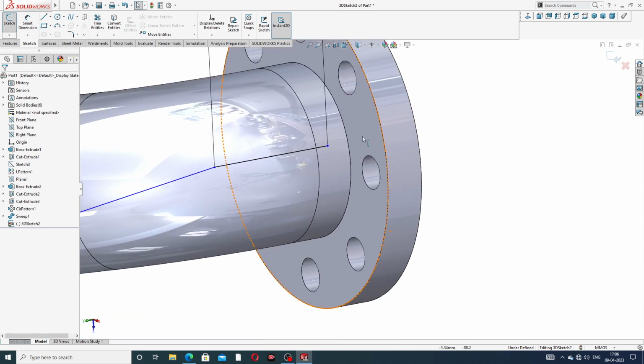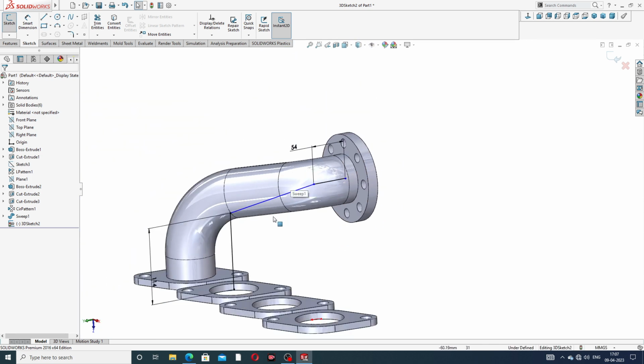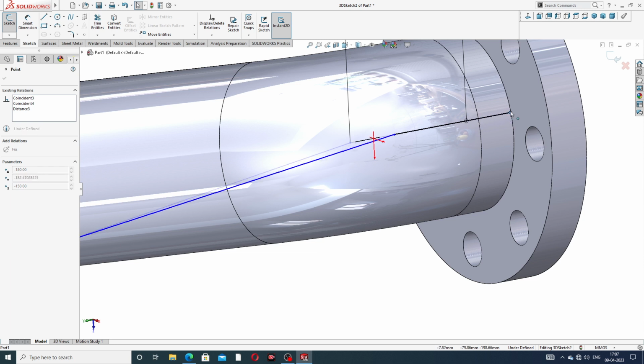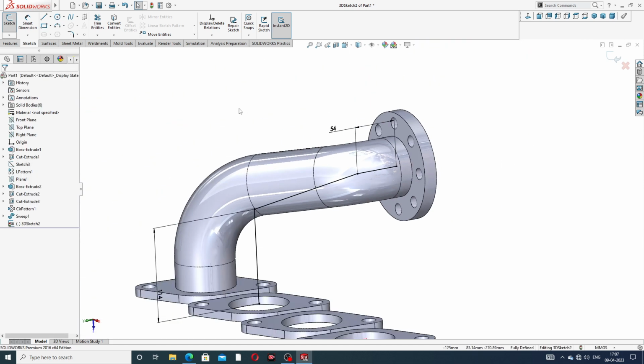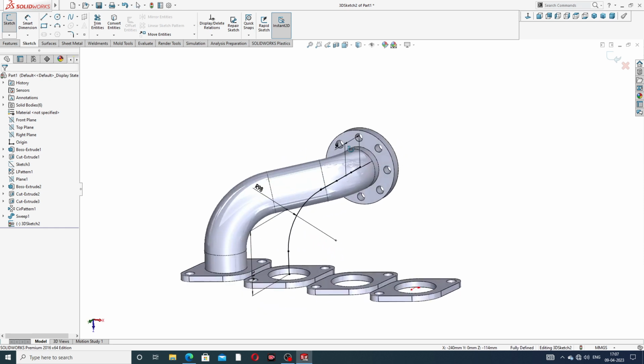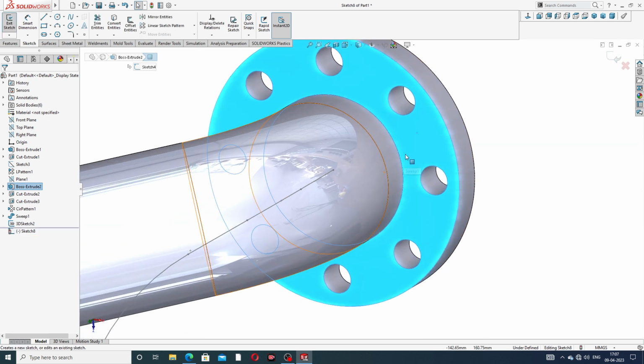And okay, this point, drag here and connect to this center, and this center is perfect. Okay, and this is dragged here, and okay, this is perfect, and also use a fillet of 68 millimeter here, and 98 millimeter here. Okay, this path is drawn here easily, and also exit and click this face, sketch, and use